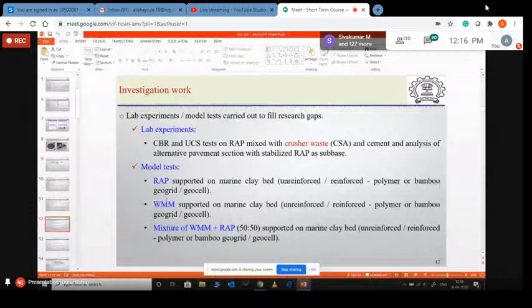Now, these are the two compositions which we have taken, and for this we have taken 10 MSA design traffic, I mean a relatively less trafficked road, with a very low subgrade CBR value of 3%. We found in marine clay 2.5 to 3% CBR. And then from IRC 37, this was the composition we got: 40 BC, 90 DBM, 250 WMM, 380 CSB, and 500 subgrade. This is the composition.